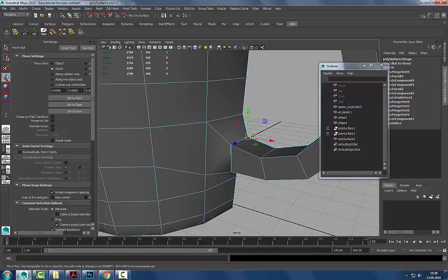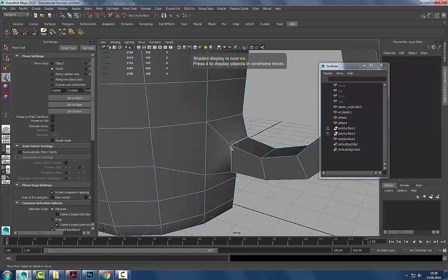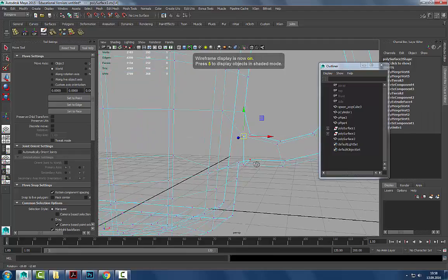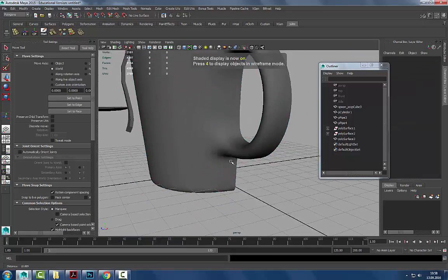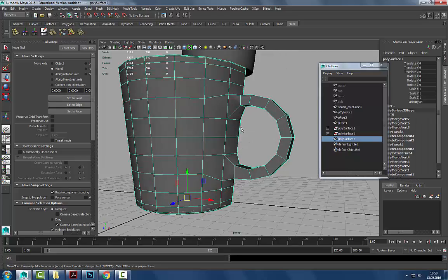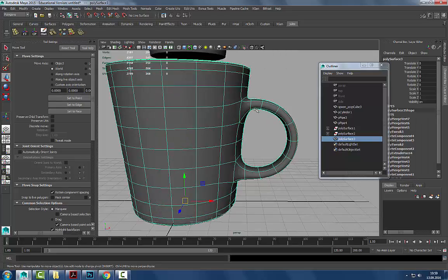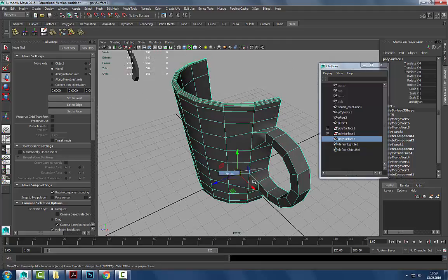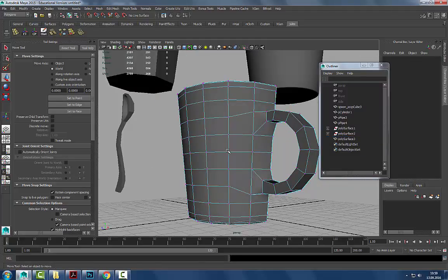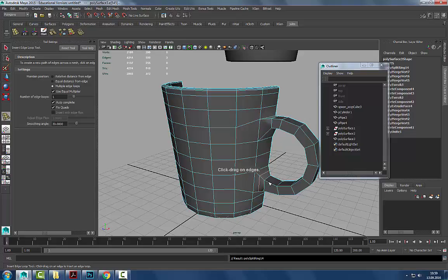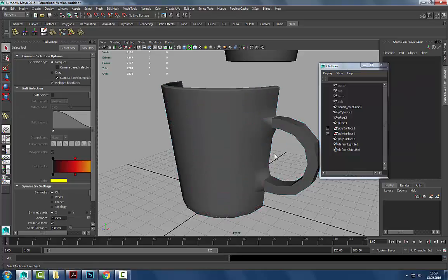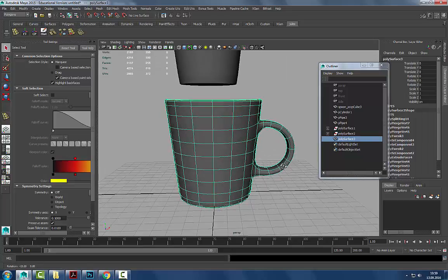So in Maya, if you want to use the same tool or the same operation again, because I just merged, I can press G. So if I go G, I'm just merging again. So I can merge several ones at once. Also, there we go. And then, this transition and the way this looks aesthetically is something that you would have to keep massaging. It just depends what the mesh looks like. Obviously, the distance between here. If you wanted maybe to experiment with having an edge loop there, what would that look like? What would that do to the subdivision result, etc.